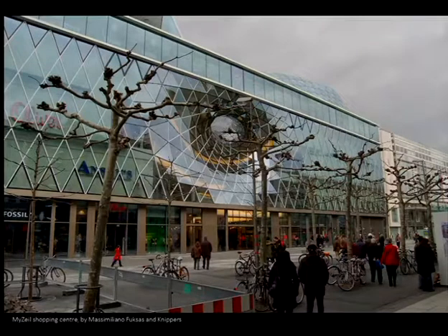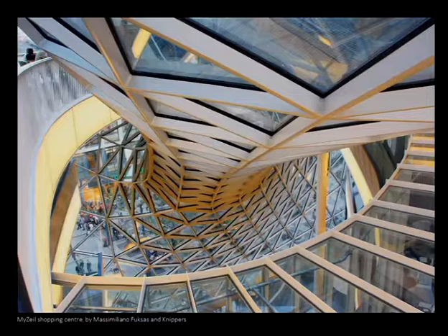There are other situations in which the shape is completely freeform, but we are still keeping the same type of approach. You see here, this one is the Milaneo shopping center in Frankfurt. The facade is completely planar. Until this point, we've got quads, just diamonds. Then it becomes doubly curved, and the quads become triangles. And when we go inside, they're all triangles. Again, the thickness is rather reduced, so here we're talking about something that is less than 10 centimeters.